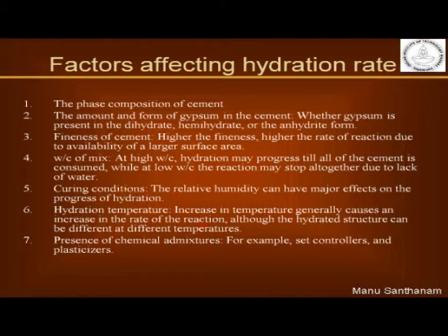Hydration temperature. So when you increase the temperature, you increase the rate of hydration. Many of you must have heard of steam curing or heat curing, that is commonly done in precasting applications. They take concrete and put inside a heating chamber or steam chamber, which produces steam at a high temperature, and that high temperature actually heats up your concrete and increases the rate at which the reaction happens.